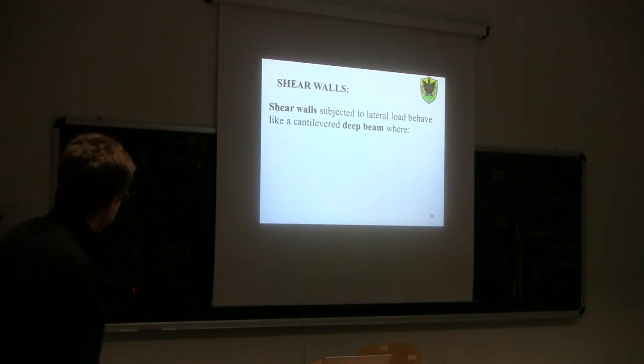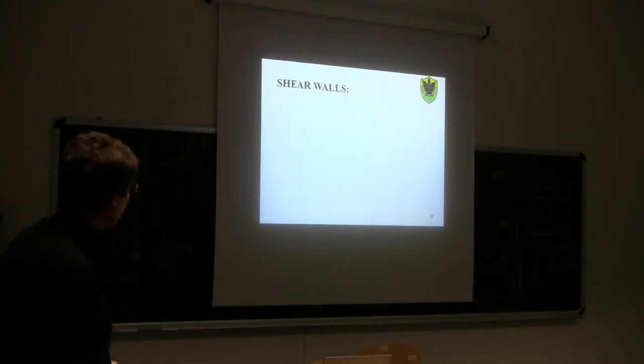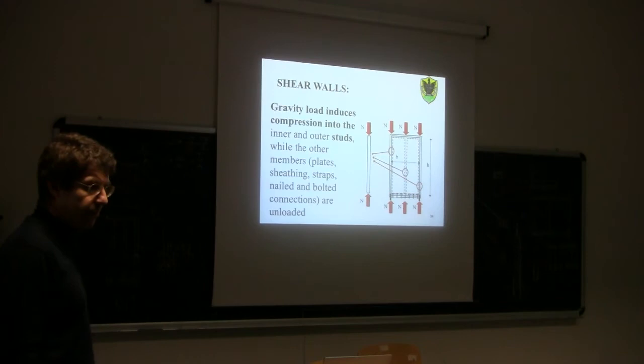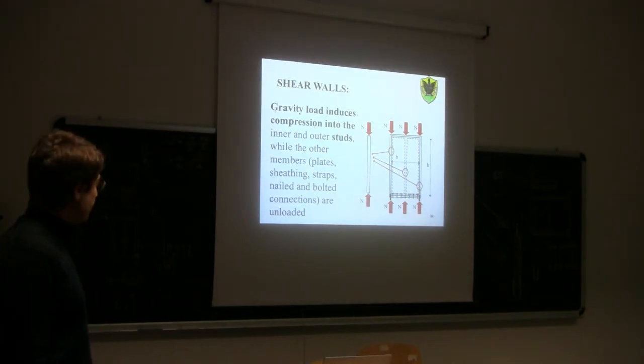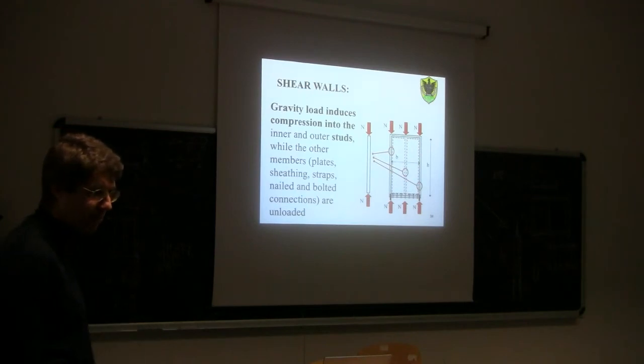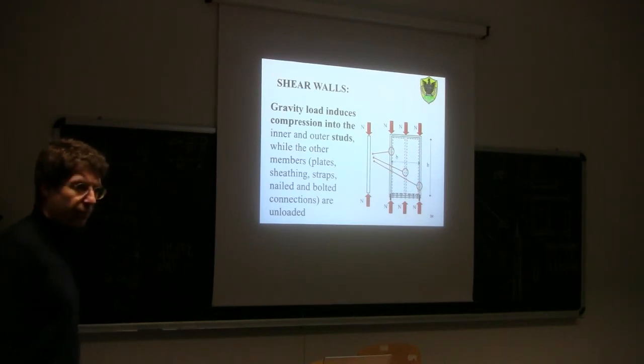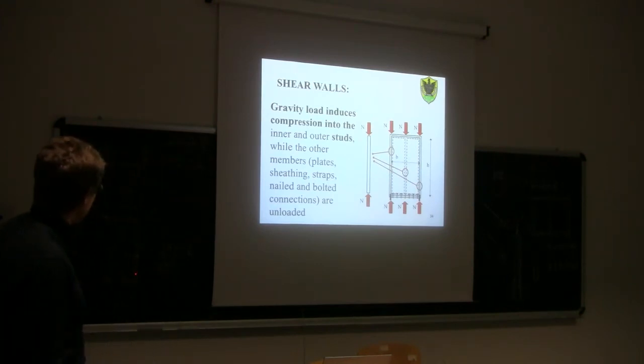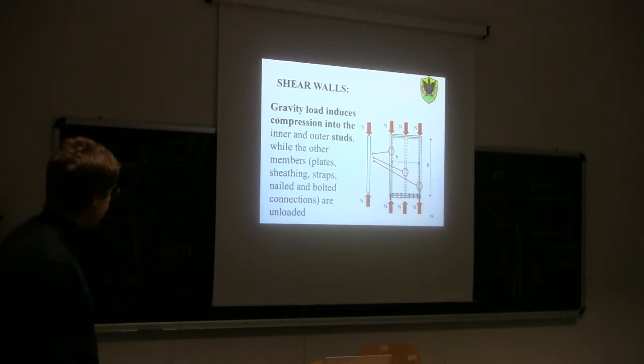Well, no, but now I'm talking about this hold down strap. This one that we saw before. This one. Do we need to do any check here, in compression? Yes or no? But what did we say before? If I have compression here, do we have a significant amount of compression going down the strap or not? No. So we don't need to do any check in the strap, at least in the compression part.